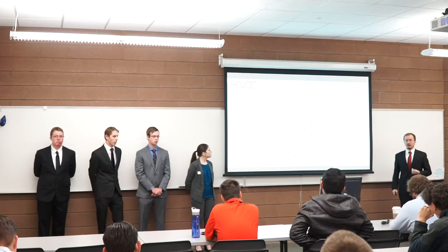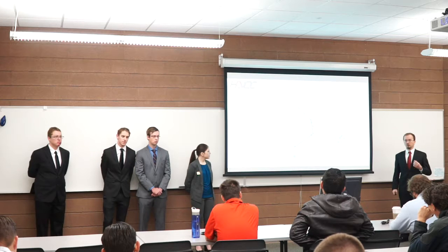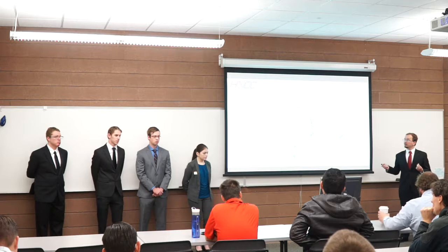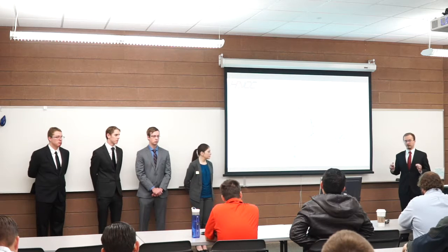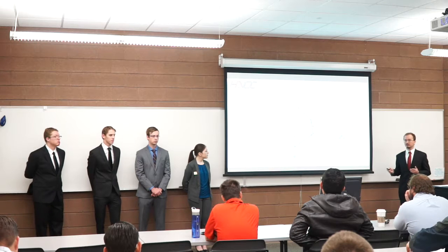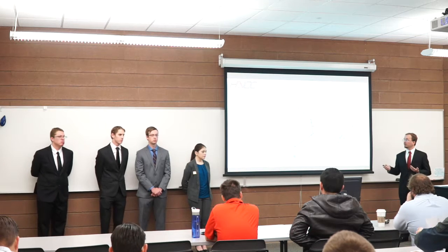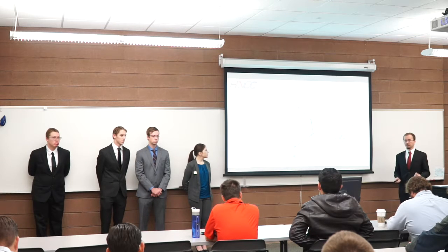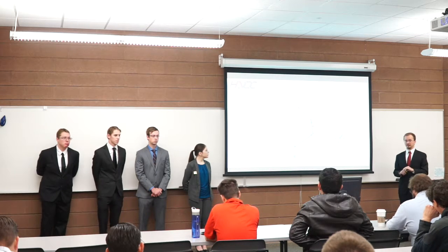For the thumb, as the shape of the thumb and the way it actuates is very similar to the other fingers, the kinematics involved with it are very similar as well. However, the only difference is that it actuates around different axes. For the thumb, when it does a tilt, it will do it around the z-axis. And when it does a bend, it will do it around the x-axis.